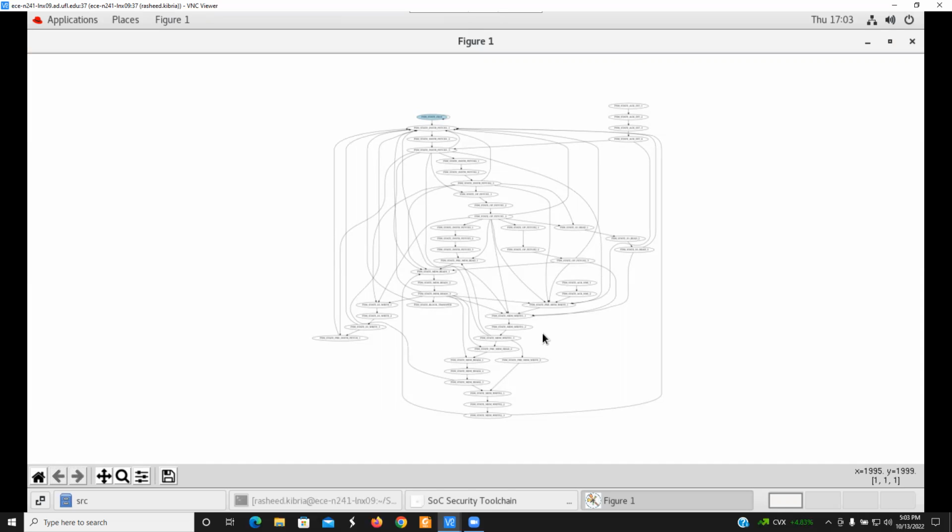What is basically done here is that all the RTLs are compiled first, and then the abstract syntax tree is generated. RTL-FSMx analyzes the generated abstract syntax tree to extract the control FSM from there. The runtime mentioned here is for compiling all the RTL designs plus the FSM extraction process.